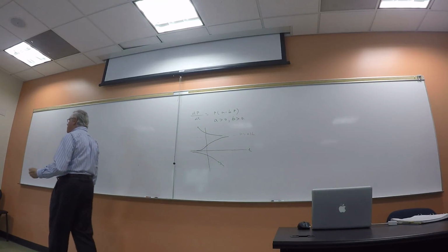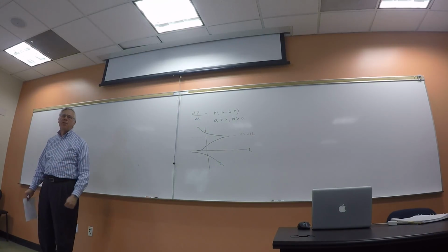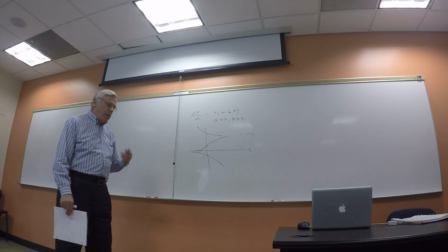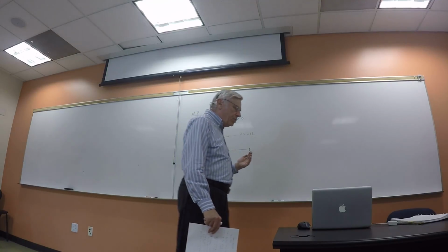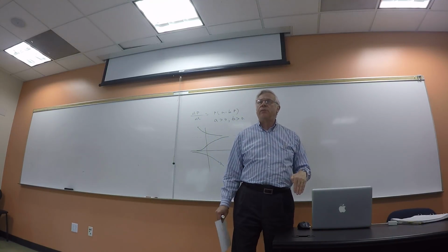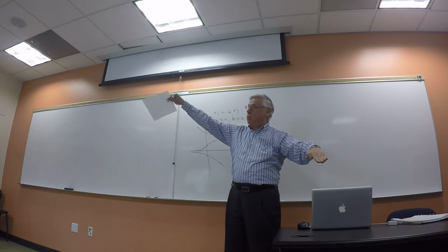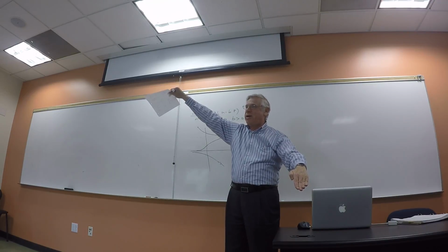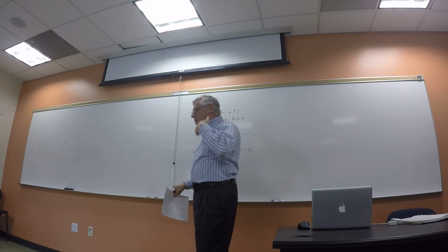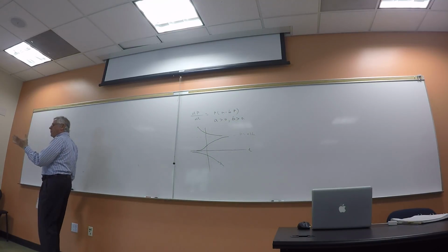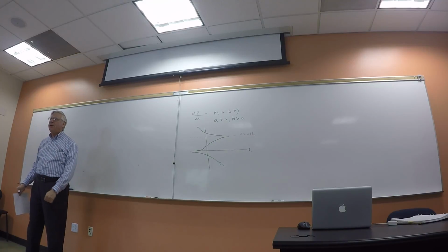It measures all these things like the attitude and the speed, and the angular displacement, and then signals are sent to counteract that disturbance. So, for example, if a whole bunch of people run to this side of the plane, normally it would just go like this, right? It would roll, okay? Then the gyroscopes on board are commanded to spin up, so they give a torque the other way to balance that out.